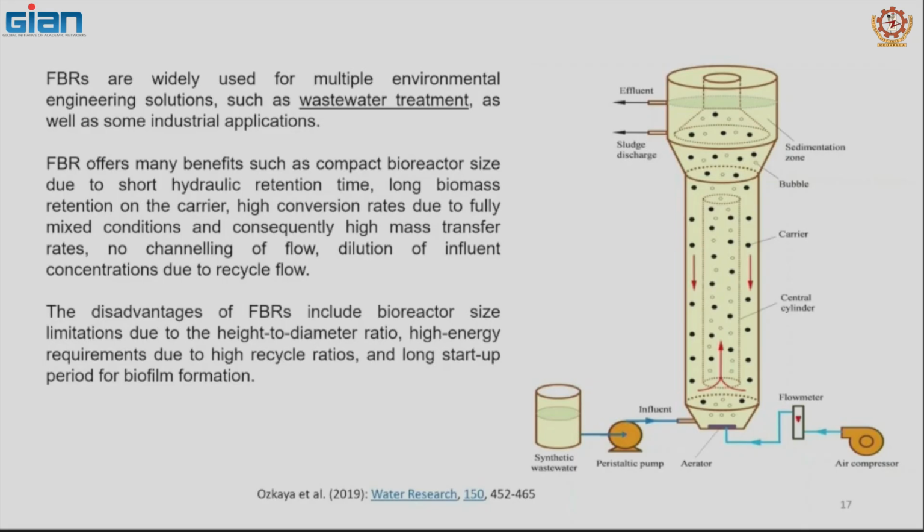The compact bioreactor size in the case of a fluidized bed is due to the short hydraulic retention time, long biomass retention on the carrier, high conversion rates due to fully mixed conditions and consequently high mass transfer rates, no channeling of the flow, and dilution of influent concentrations due to recycle flow.